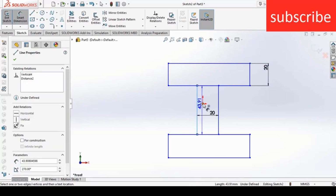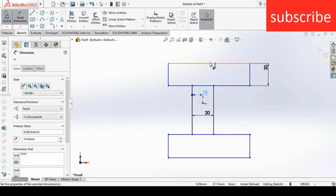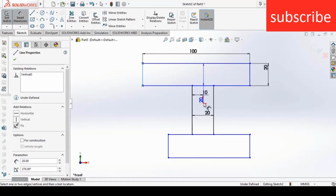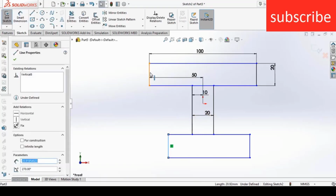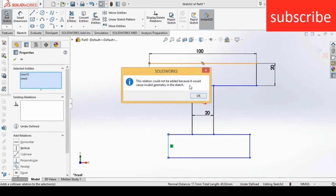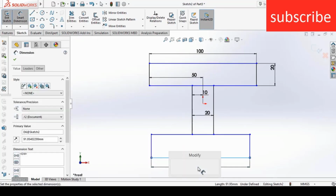Here select this line at the center, enter the value of 10 mm and 100 mm, let's say 50 mm, escape, make it horizontal, press Ctrl plus Z, select these two lines by pressing Ctrl.